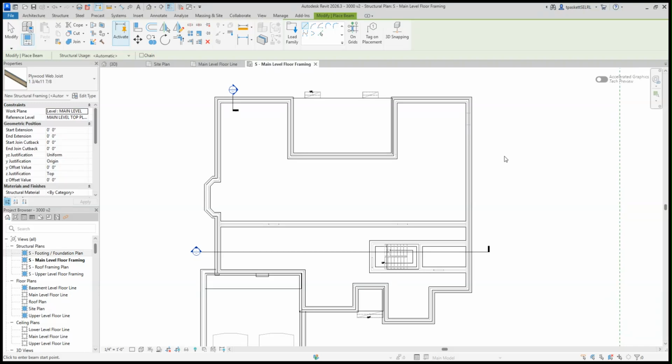And then your various heights. And then the other part that changes a lot is here on the flange. So you got a top flange and bottom flange. The dimensions on those do change depending on what depth you're using to give the better strength to it. Now, almost every house is going to use 11 7/8 if it's around 3,000 square feet. So that's going to be your common size there that you're looking for. So once we get done with our sizes and pick it out, we go to sheet 7.